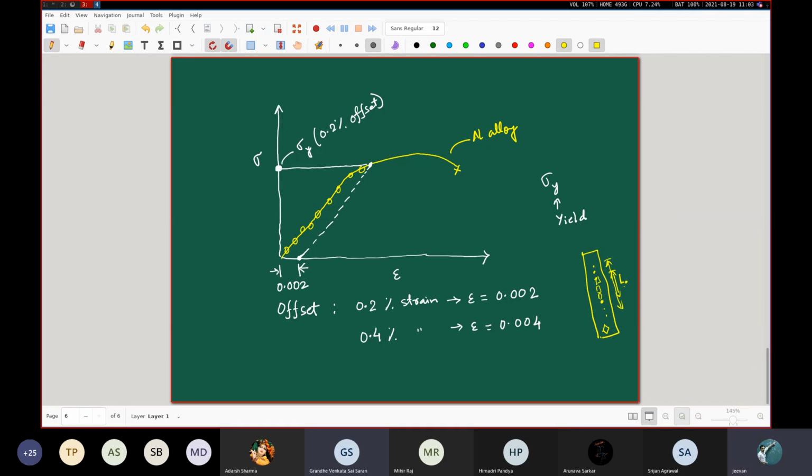You're absolutely right. This epsilon value that we are saying is more like the kind of thing that you studied in your high school. And just now the question that we had regarding the strain gauge, the calculation of the value of the strain using a strain gauge would be more in keeping with the formal definition of the strain, because strain is actually theoretically defined at a point. But when you are writing this strain, it is more like we are saying it as a relative change in elongation, considering actual non-infinitesimal lengths.